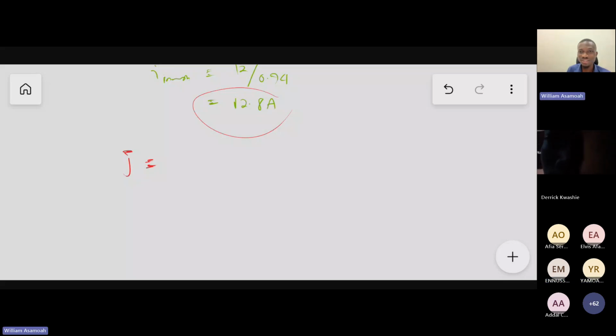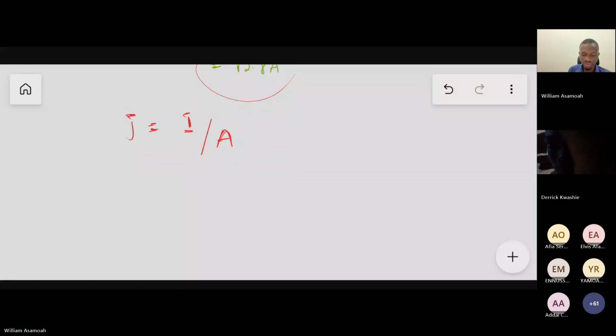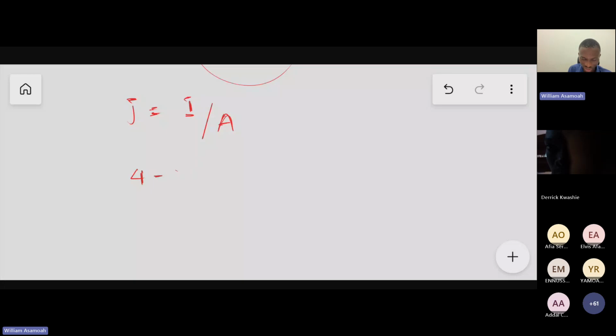Physics, current density is equal to what? So we don't remember. Okay. It was one of those confusing parts of physics we didn't remember. Current over area, right? It's called the current density, J. Now, for automotive, what we recommend is that all your current densities should be between 4 and 8 amperes per millimeter squared.